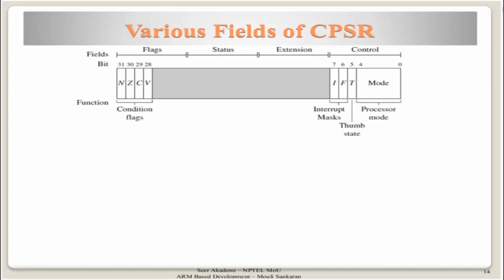That means we are not supposed to write anything into this. If you do so, you are doing it at the risk of preventing your program from running on future processors. The future processors, and it's not just may, it is already the case, have used lots of bit positions in this location. In ARM7TDMI, if you try to do something into this location, as long as you are running your code on this processor, there is no issue because there is nothing important there.